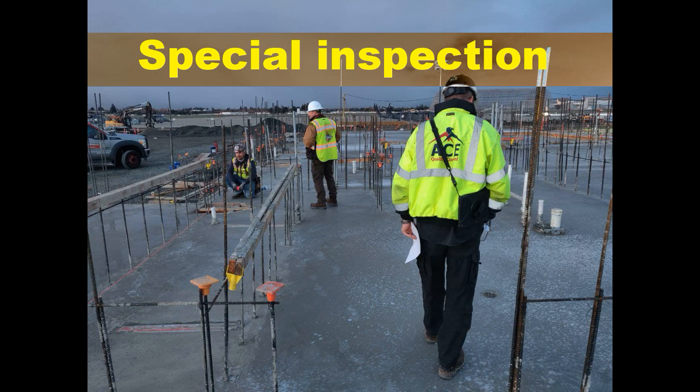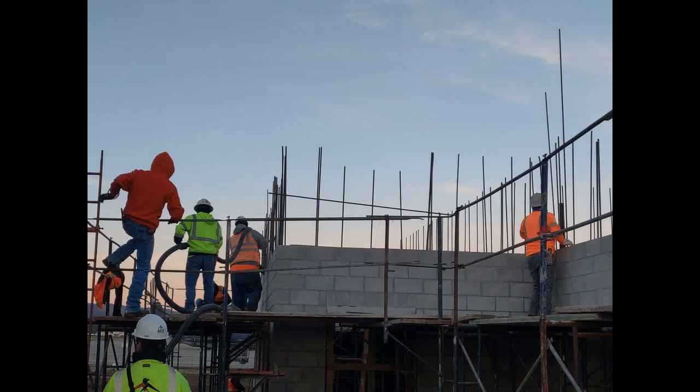Maintain a 3-ring binder for the Special Inspector's daily and bi-weekly reports and the Special Inspections Project Manual. This file must be located in a conspicuous place in the project trailer or office to allow review by the building official or contracting officer. Discrepancies that are observed during special inspections must be reported to the QC manager for correction. If discrepancies are not corrected before the special inspector leaves the site, the observed discrepancies must be documented in the daily report.